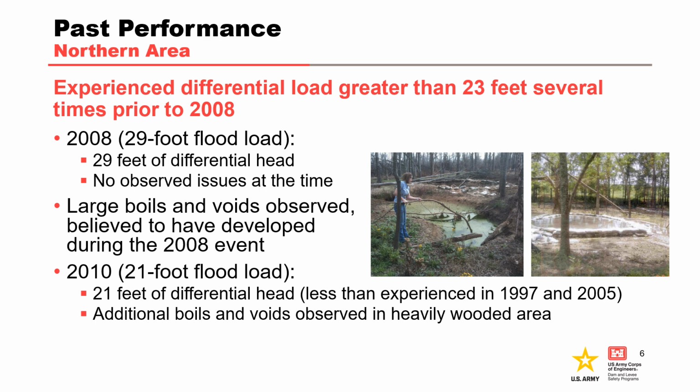This was the new highest load to date experienced by the embankment, although it should be noted that very little records exist for prior historical floods. At the time of the 2008 event, no performance problems were observed in the area. In February of 2010, a local landowner discovered several voids on the land side of the levee that were observed to be as much as 20 feet wide and 10 feet deep. Although no performance problems were observed at the time of the flood, Vicksburg District personnel believe that these voids may have formed unobserved during the 2008 event.